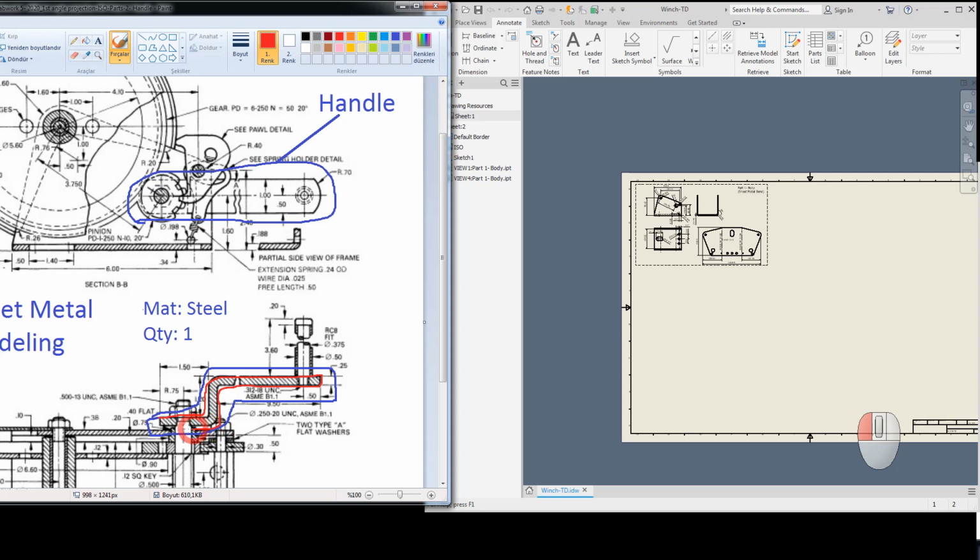During this part creation, I will just draw this outline, and I will just make a 1-inch extrusion, which you have seen here. Let me draw this again, and I will just make the shapes and have these holes, hole features, which you have seen here. One is at this point, the other one is at this point. We will create that details later on. We will just start with our part.